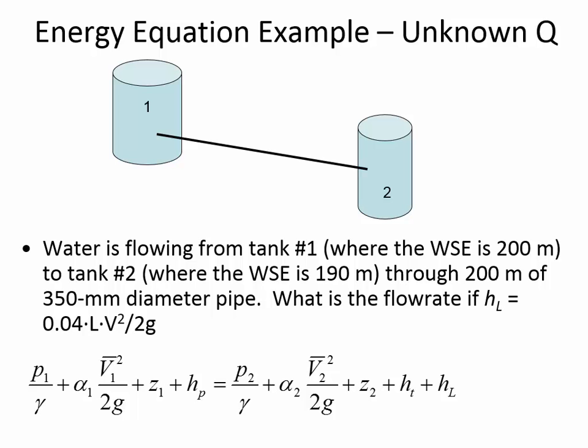We're going to spend a lot of time in next semester's hydraulic engineering class actually finding ways to calculate the head loss due to pipe friction. And the golden standard for that, as I've already told you about, is the Darcy-Weisbach equation. That's the one when you first start up WaterGEMS, you have to switch it from Hazen-Williams over to Darcy-Weisbach. And Darcy-Weisbach says that head loss due to pipe friction is f L V squared divided by D 2g. This is the Darcy-Weisbach.